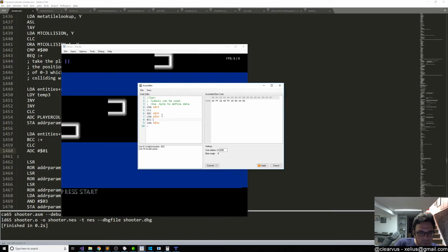Branch carry clear to A, and this is A. Branch carry clear. Huh? That should be okay. What doesn't it like about my label? What syntax? Labels can be used. Okay. Oh, it's because it's A, and that's a register name. Never mind. So we'll change that to M.